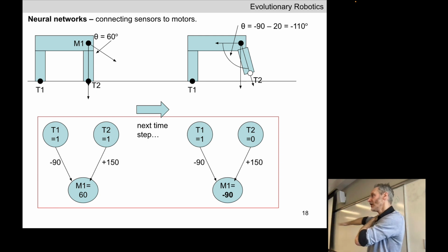So there are 2 rotations allowed. You can set the 2 joint normals for a universal joint to define what those 2 degrees of freedom are. Maybe you want to allow this motion and this motion, or this motion and this motion. Make sense?